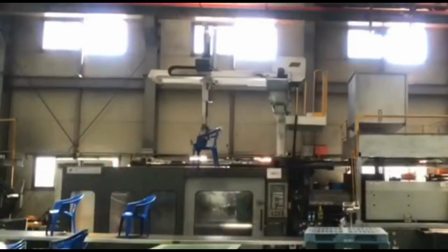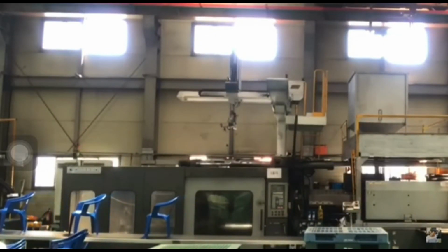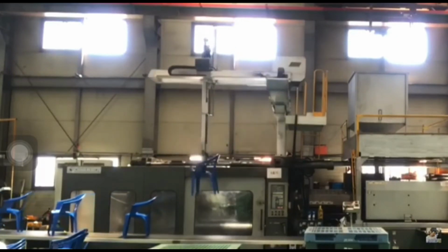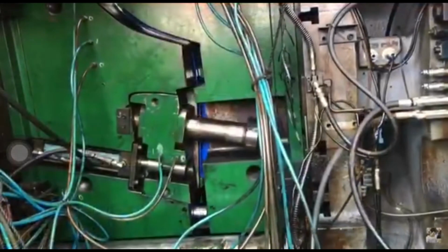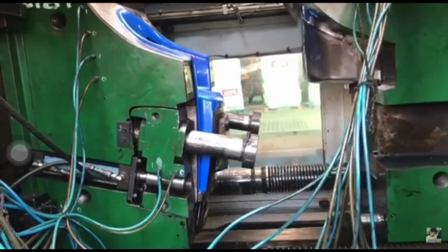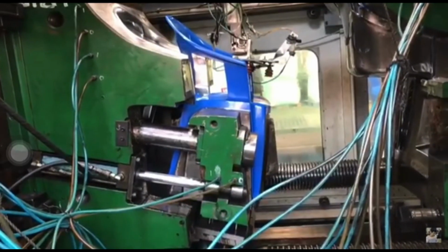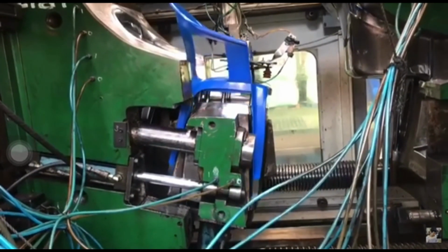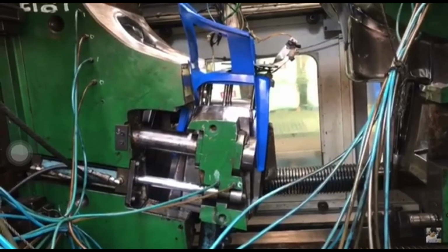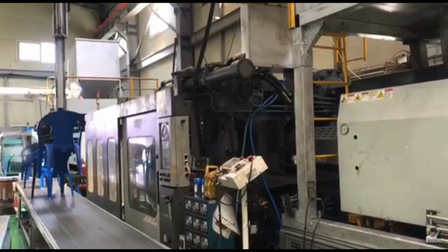The third advantage is that it is very fast. Cycle times can be as low as 10 seconds. Combine that with a multi-impression injection molding tool and you get a lot of product very quickly. The part above takes a bit longer as it is specialist material and has a lot of features to be molded correctly. But at about 50 seconds, you still get 70 parts per cavity per hour. CNC machining a one-off would take half a day. 3D printing it even longer.